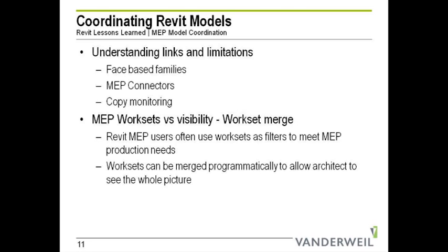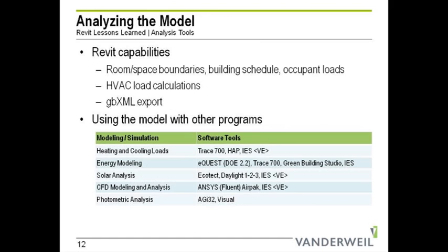If you're dealing with consultants and you're seeing things on one view and not another, it could be caused by the work sets. And starting in 2011, you can now look at the work sets and turn them on and off. But before that, you were just lost and had no way to control it. On to analyzing the model.